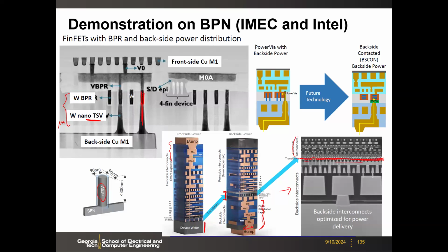And then you have the top routing, the front side routing, and back side power delivery network. And you see it's very large in terms of the wire width. Typically nowadays they propose the backside power delivery network, maybe 3 metal or 4 metal layers.